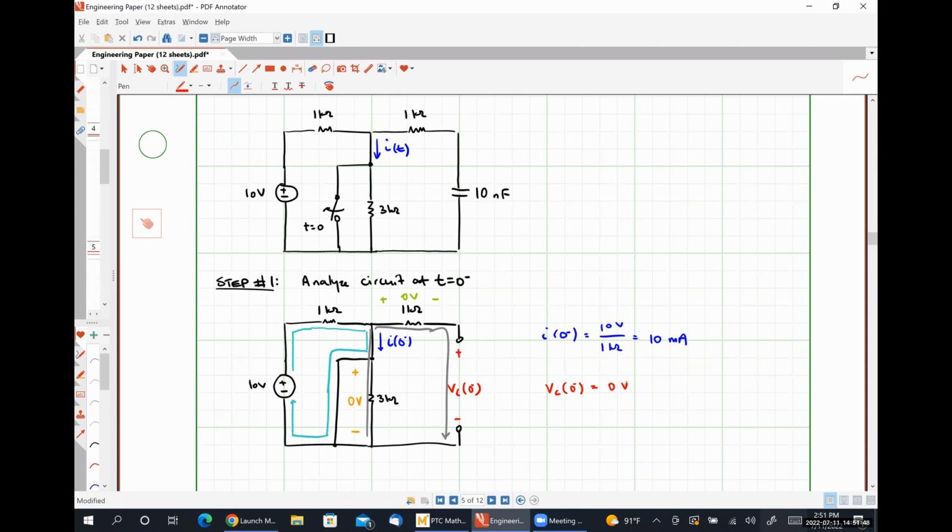All right, so let's move along. Could we have said VC is equal to 0 because of the open circuit? Unfortunately, no, Devarier. So the voltage drop across a short circuit is always 0. For an open circuit, we know that the current flowing through it is always 0. The voltage could be anything. In this particular case, our open circuit voltage came out to be 0 because of that Kirchhoff's voltage law loop equation, where the voltage drops around that closed loop turned out to be 0.